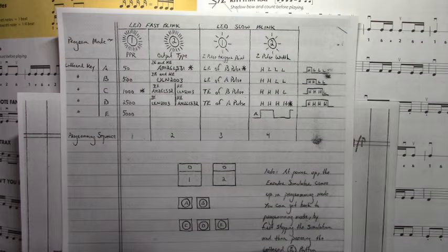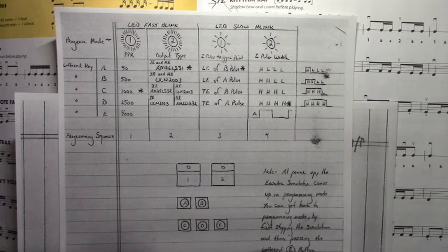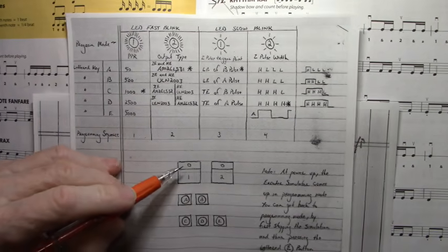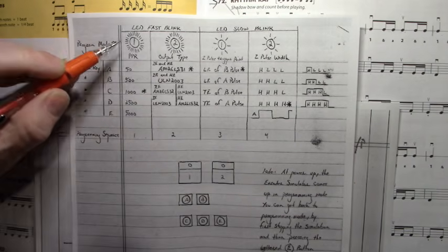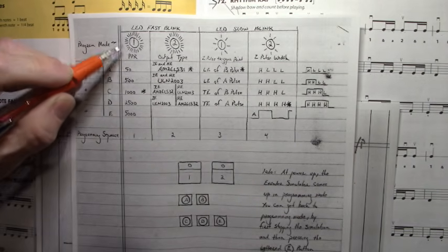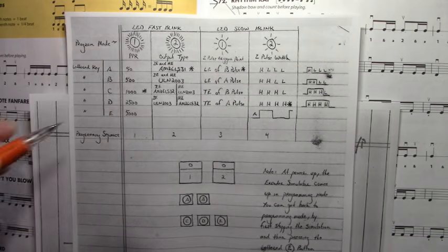Let's talk about the controls and switches that set up how the Hall effect encoder simulator operates, how it will perform as a feedback device simulating your motor. When you first power up this tester, this LED right here in switch number 1 will be blinking fast. And that's when you want to set up your pulses per revolution.